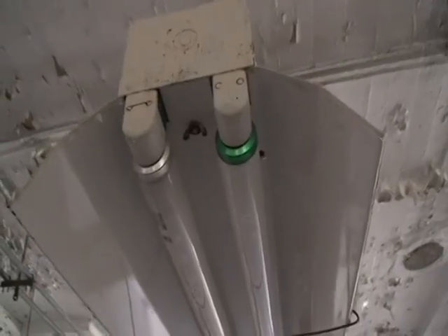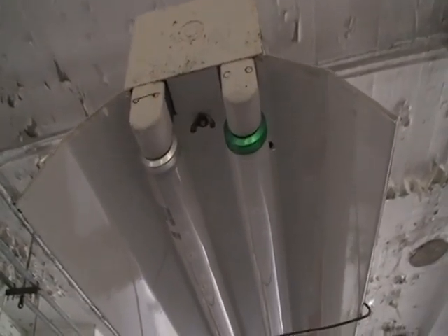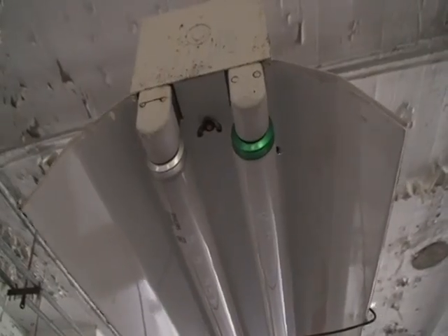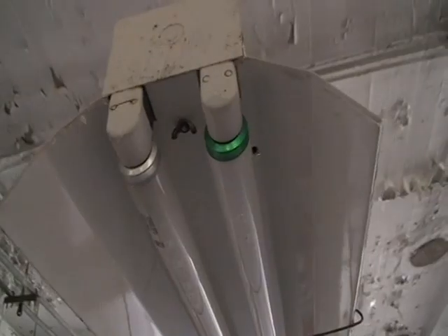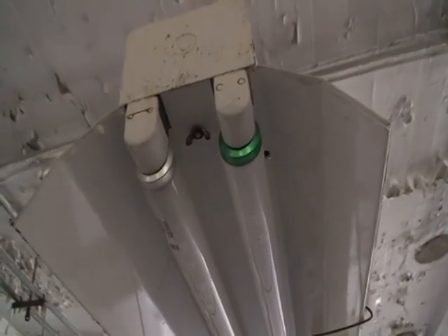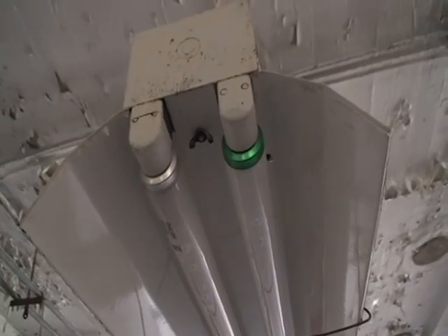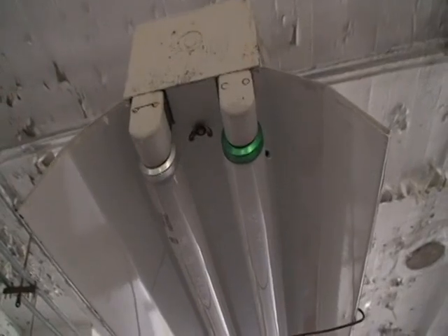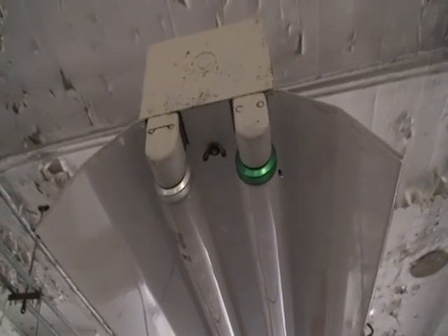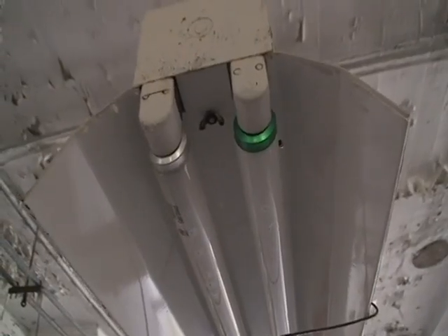Here's an example of a couple of different types of fluorescent bulbs in a fixture. As we said earlier, chances are quite good you need to consider the possibility of PCB ballast in these lights as well. If you look at these two different kinds of bulbs, you'll notice the ends are different. One has a green cap, one has a silver cap. The silver cap one is an older bulb. It'll have higher mercury content, higher metal content, and the vapors in it. The green bulb is a newer bulb. It's a lower mercury bulb. Both of those would still be considered a universal waste under RCRA.